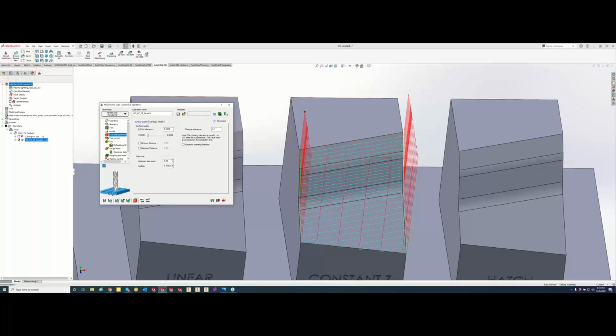Now, the step over is going to also indicate what surface finish you're looking for. So there is a calculation that goes, and maybe Greg, you can help me out here, but with the step over, we will get a scallop of 5 thou. So what that means is, for those of you guys that have a, trying to think, the surface finish, RA call out, can't think of the name of the instrument that they use, profilometer.